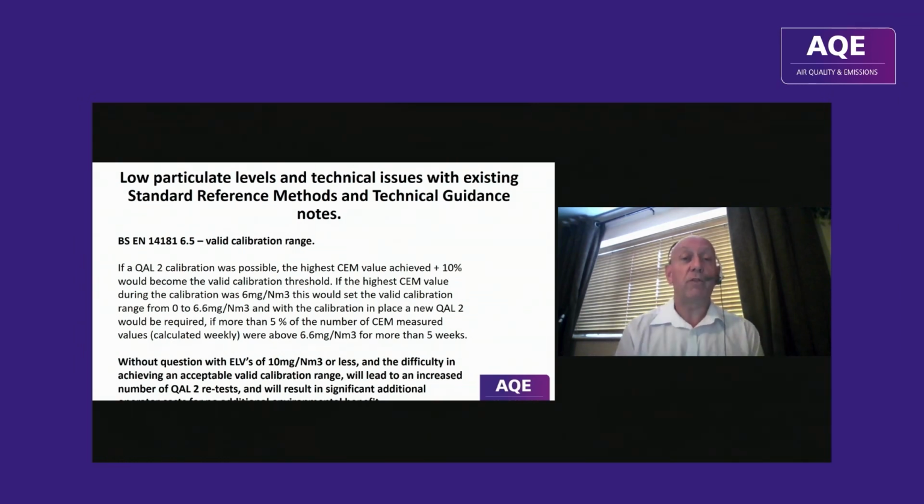So with these sort of caveats in place, without question, with emission limit values of 10 milligrams or less, the difficulty in achieving an acceptable valid calibration range will lead to an increased number of QAL2 retests and will result in significant additional operator costs for no additional environmental benefit.